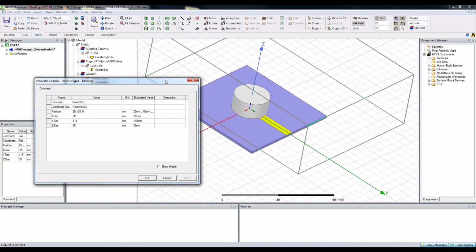Okay, and as for PML, it is very intelligent and it doesn't need this condition. So even with a smaller size radiation box, PML can work without satisfying this criterion. But using PML is resource consuming. For example, it would take a lot of space of your RAM and CPU resource.